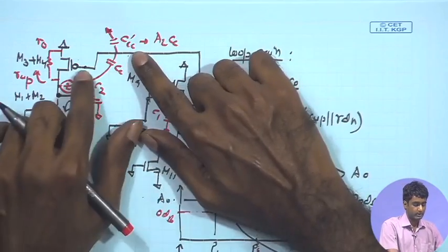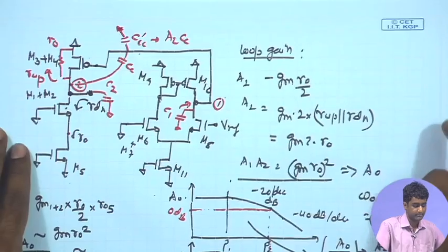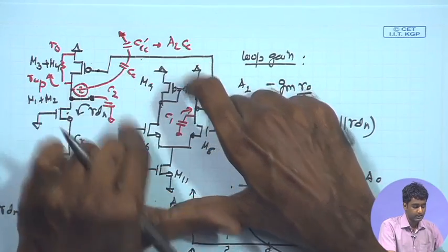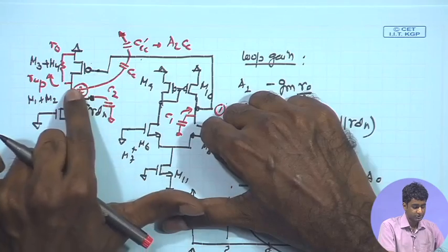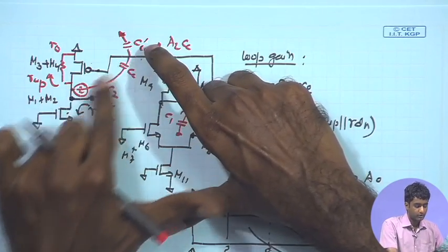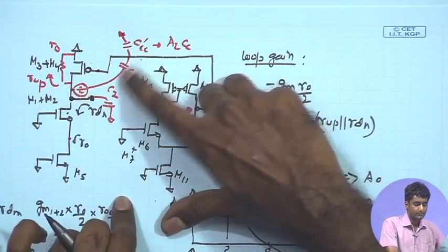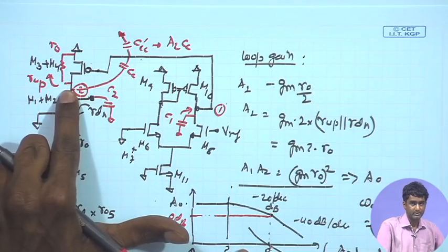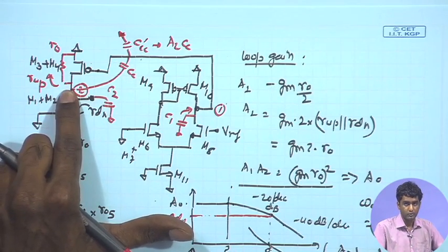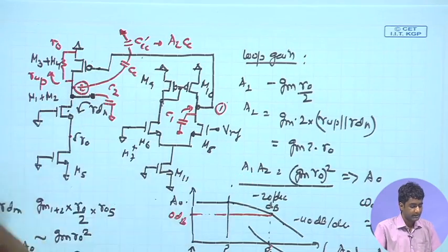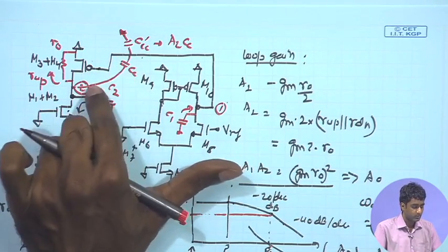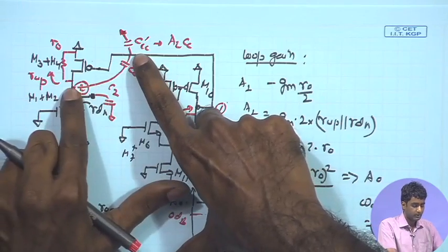As we will see in another example, a sufficiently large capacitor connected between the gate of the PMOS transistor and the output node produces a low impedance path between the gate and the output at higher frequency, maybe close to P2, as a result of which the impedance looking into the output point becomes smaller.